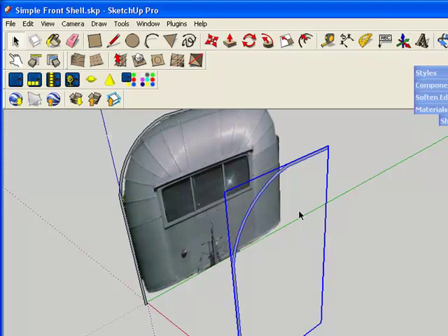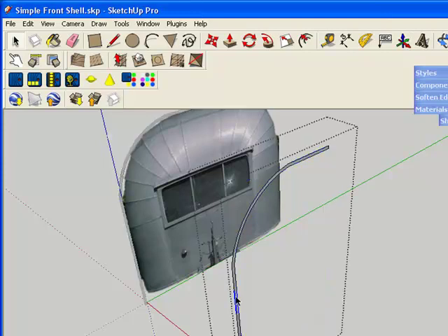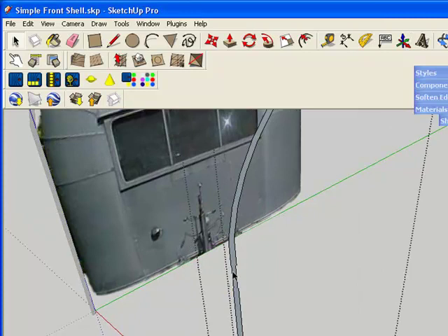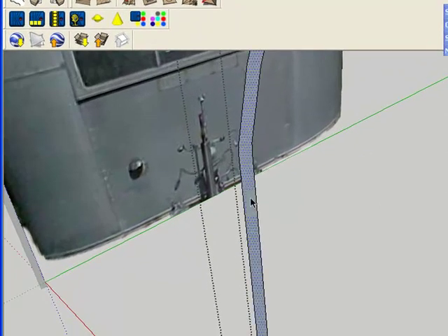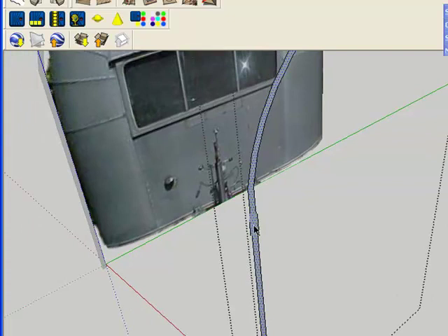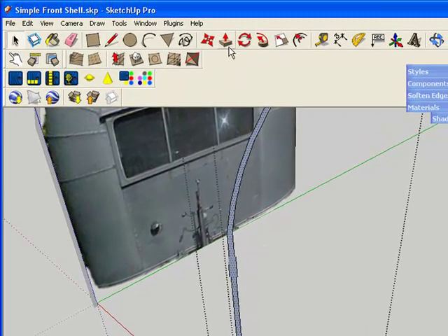What we want to do next is I want you to double click on the selected pattern, and then use your scroll key, roll in, and click again so that you can see you just have the gray intersection highlighted. Now we want to use the pull tool to extend this out. The pull tool, if you look up at the top, is this little tool here. It shows us a little box with an arrow coming out of one side to show that we could pull this or stretch this. You can get this tool by pushing the P key, or in this case I'm going to go back and just push on the tool